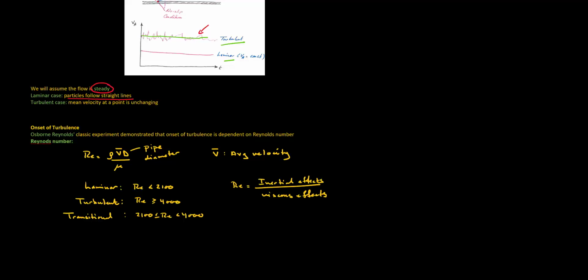In turbulent flows, instabilities cause small disturbances to an otherwise steady flow, and these can grow into observable fluctuations, as we've shown in this image over here. On the other hand, for a laminar flow, the viscosity dampens these small disturbances and the flow remains steady. And as we've mentioned from this dimensional analysis, as the Reynolds number increases, the relative significance of the viscosity decreases.